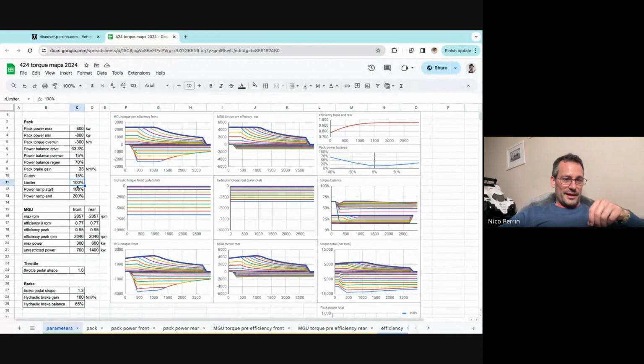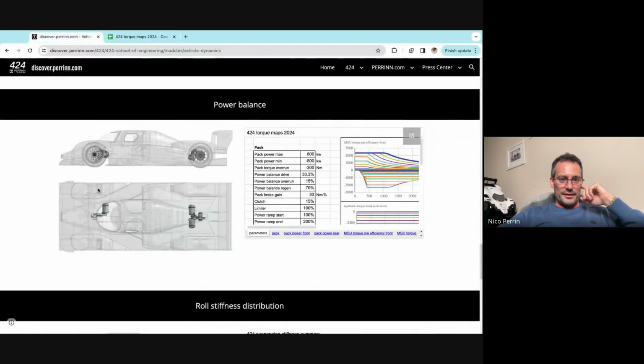We also have things like, well, because I'm showing this, the speed limiter is this parameter here. When we change the speed limiter for these sections, say I put 70% of the speed, you see how it cuts the power based on speed? That's how our speed limiter works. When the motor speed reaches a certain amount, it cuts the power automatically. I can go into more detail, but I won't go into much more today.